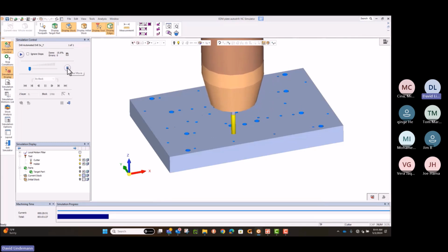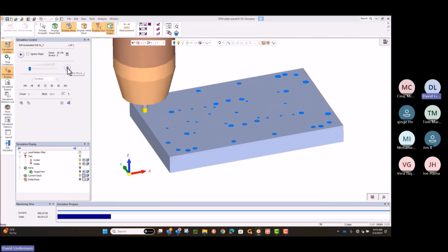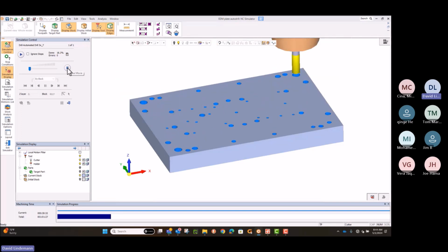If you want to crop out a line or something like that, you can. I'll come back and I'm doing a faster one. I sped it up so we can see it all. And now you can see it's already been roughed out. Now I'm coming back and doing a finish in some of those circle hole patterns. So I've got a true helical finish.